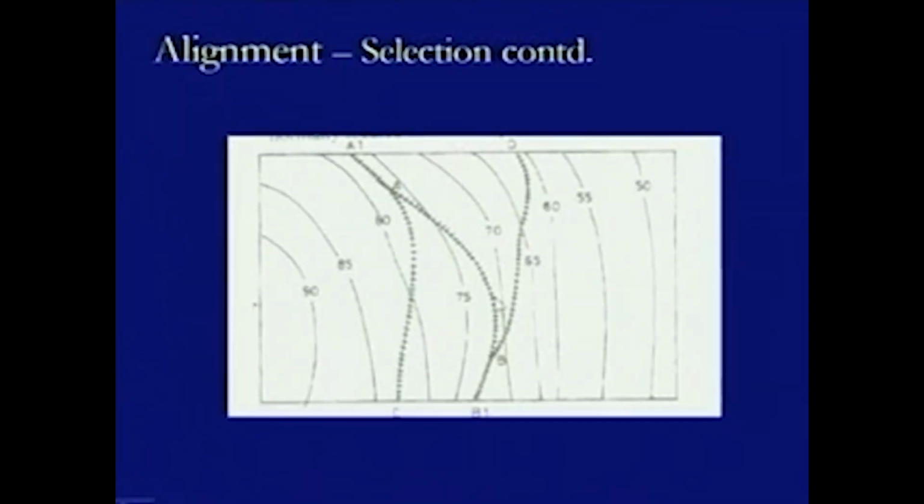Now, in this diagram what we see is the switchback development. Here what we find is this is the lowest contour on this side and the highest contour on this side. Therefore, we are trying to move in this direction. As far as the shortest alignment is concerned, we could have provided a straight line from this point to this point, but then it is observed that because of the shorter distance, probably it will fall outside the limits of the rolling gradient.